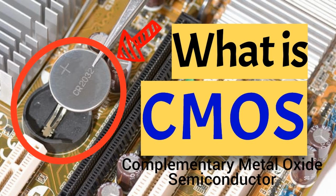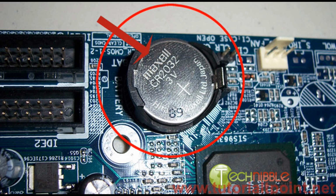Inverter operation. The simplest CMOS logic gate is the inverter, which consists of one NMOS transistor and one PMOS transistor connected in series between the supply voltage and ground. When the input to the inverter is low, logic 0, the PMOS transistor conducts, pulling the output voltage up to the supply voltage, logic 1. When the input to the inverter is high, logic 1, the NMOS transistor conducts, pulling the output voltage down to ground, logic 0.